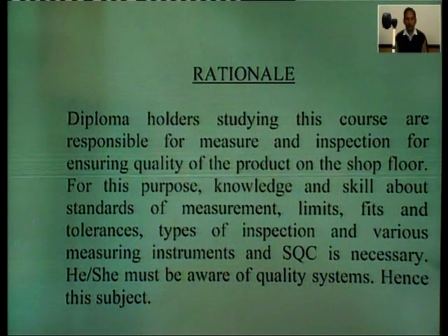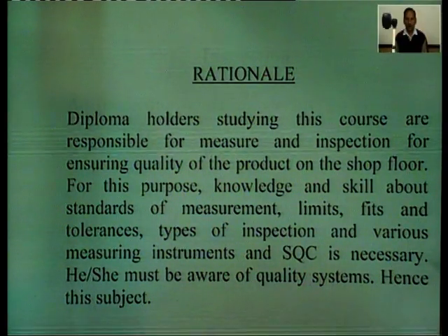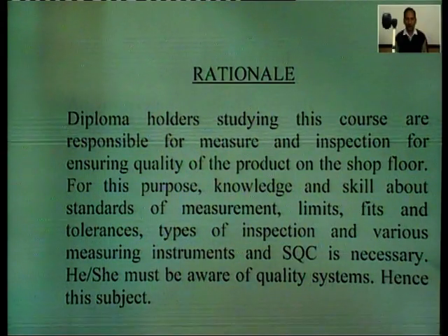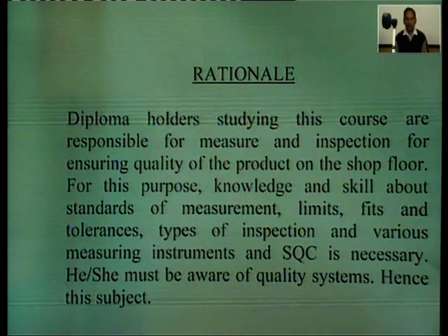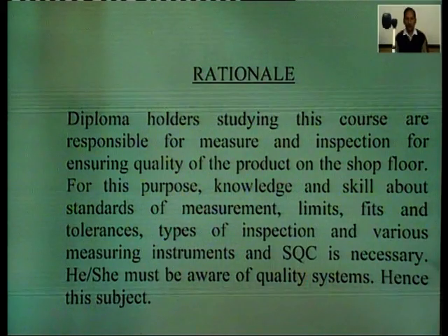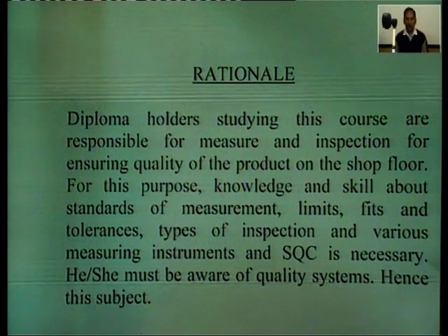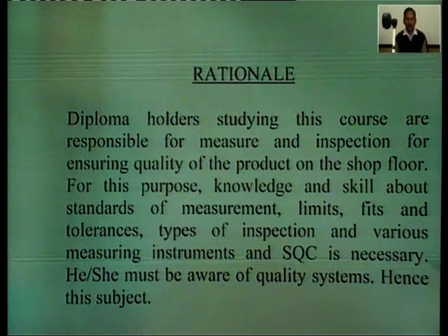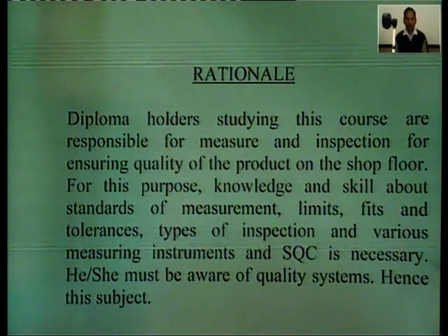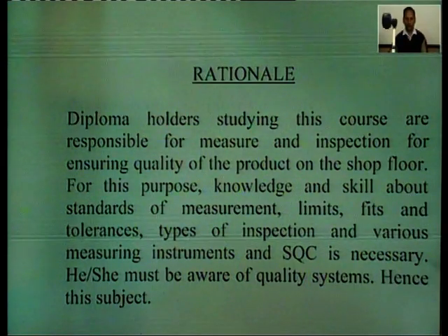So for this purpose, knowledge and skill about standards of measurement, limits, fits and tolerances, types of inspection and various measuring instruments and SQC, meaning statistical quality control, is necessary. He or she must be aware of the quality system, hence this subject.